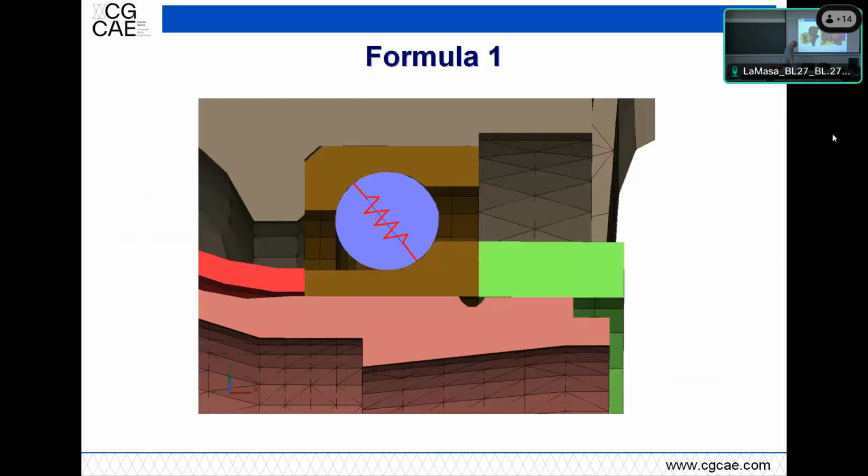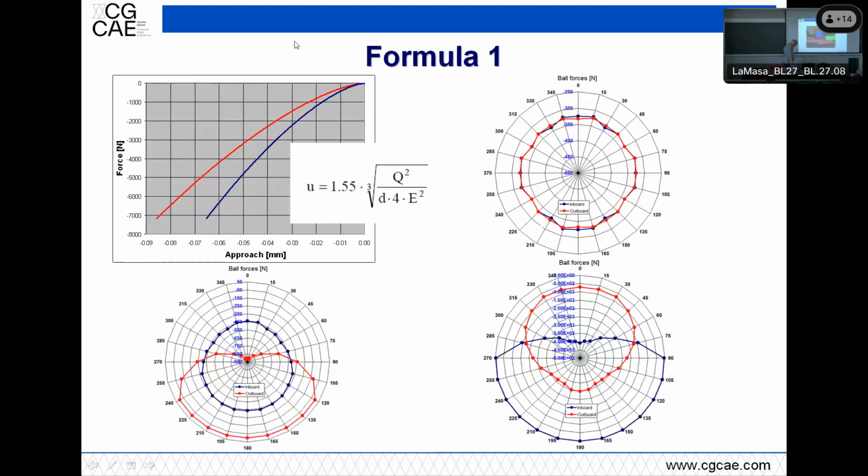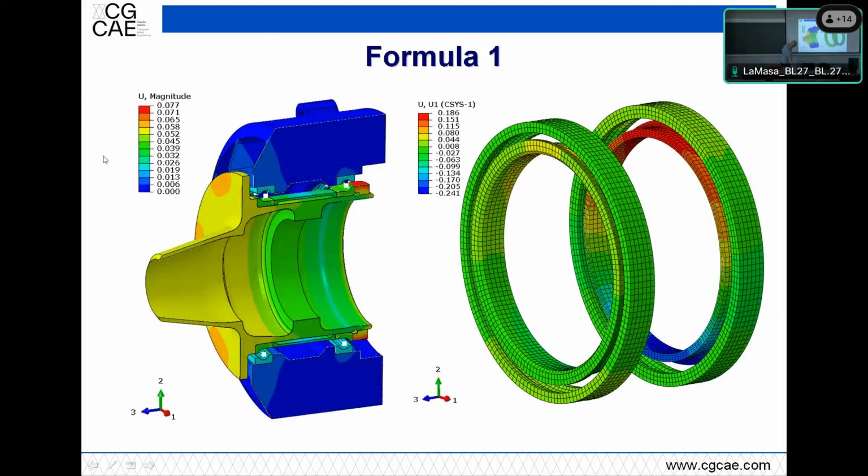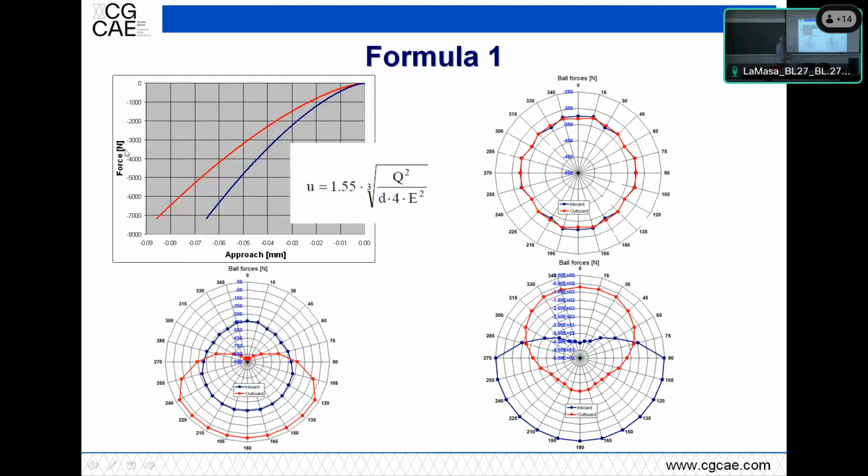And again, here working on the bearings, because at that time it was not really possible to model the sphere or the balls. I would not recommend it even in our days. I substituted this ball with a nonlinear spring, which clearly makes some approximation because it cannot move like the ball is actually doing in the rollers. But this was not important to determine the stiffness. And coming up with something like that.